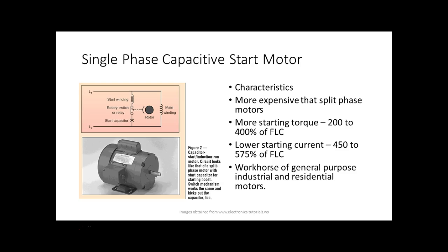So here we have no connection to, in fact, here they don't call them armature. On an AC motor, the rotating part is called the rotor. And the stationary field is called a stator. And then of course, when we talk about the parts of a DC motor, we say, okay, it's got the armature, it's got the commutator, it's got brushes, and it's got a field. And what do we forget?